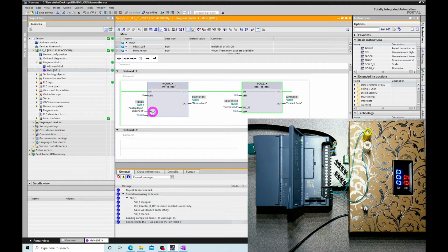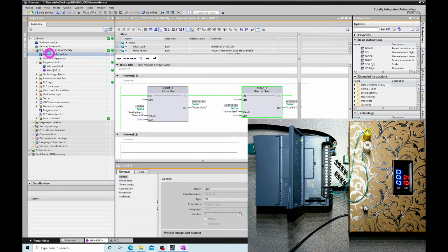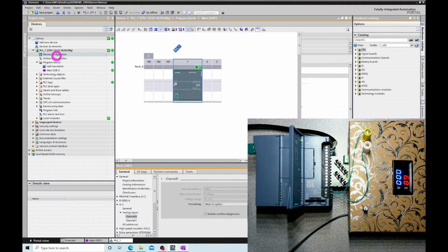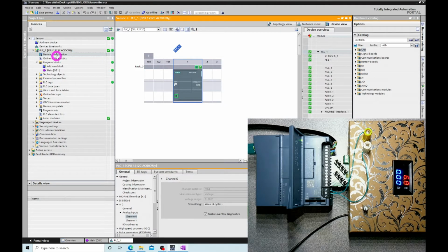The value you should address is your analog input, which for us is analog channel 0. To find that channel, click on device management, then go to the properties, then to general. In general, you see the analog inputs.